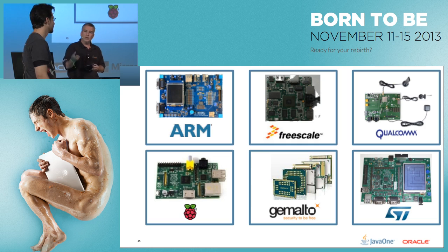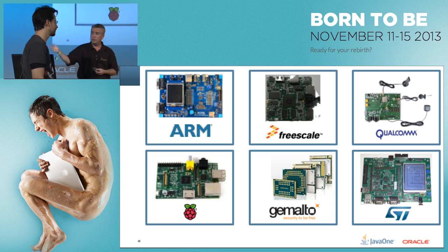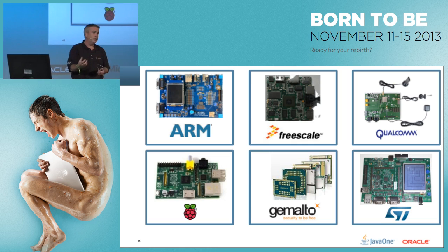The serial console information comes easily to you on a normal x86 platform. On these systems, it doesn't. So you actually have to use a serial tip to connect onto the console or the TTY port and capture the data so you can see what's going on, like get the IP of the machine because it doesn't have a head. So this is usually your really good friend for bringing up systems, doing customizations of the boot environment, like Steve said earlier about the display on the Raspberry Pi. We can actually change the U-boot environment to set different attributes of the display or the Ethernet or such.